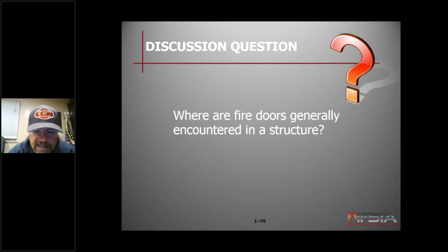process. And what this does then is these fire doors, when the fire alarm is activated, the doors will automatically close and give a higher fire protection timeline to areas of the building beyond the fire area. So it's important to understand where these are as we go into a building. If they haven't tripped yet, they may be closing behind us as additional alarms are set off or fire progresses through a building.